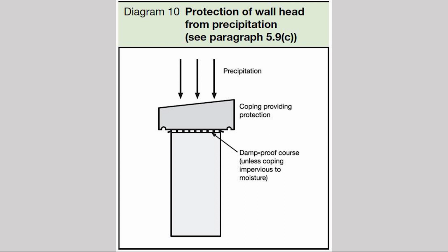And the coping stone should be sufficiently wider than the wall itself so that any moisture coming down or rain coming down onto the coping stone is pushed away from it. And then they have little nicks underneath that prevent capillary action from the moisture coming through and running under and into the top of the brickwork wall. So that's again an important detail to make sure that you're getting correct, and it's one that we frequently see as being an issue.